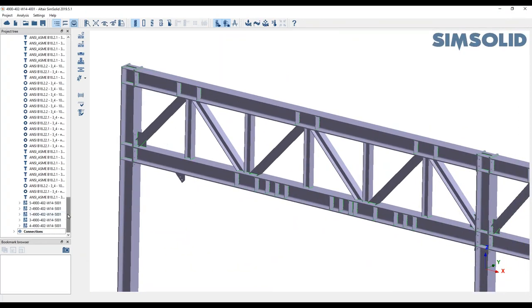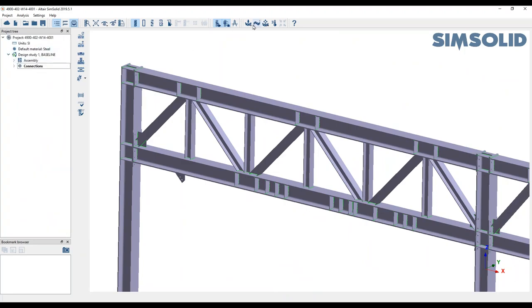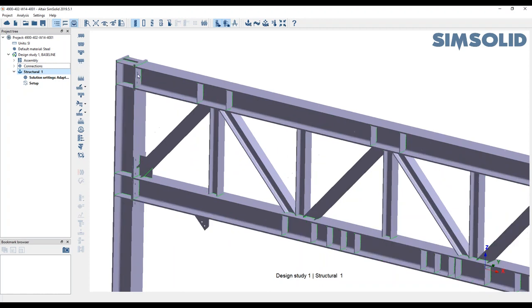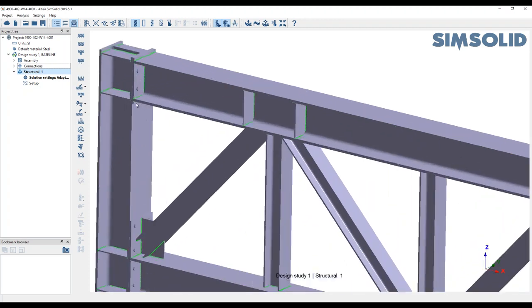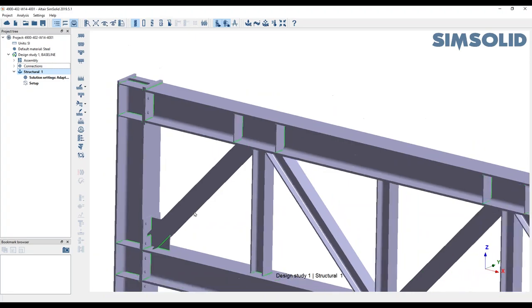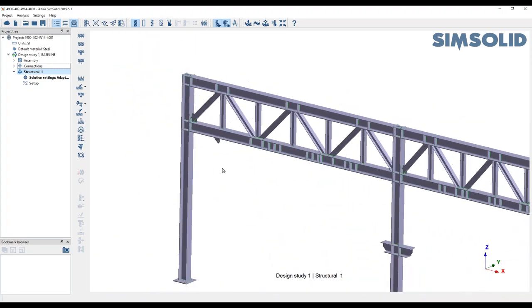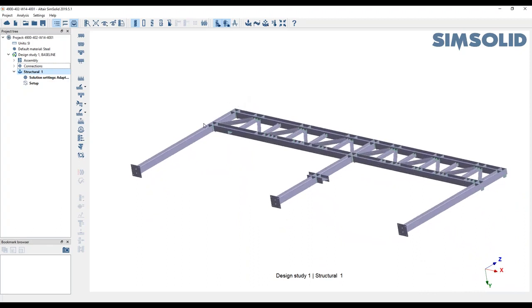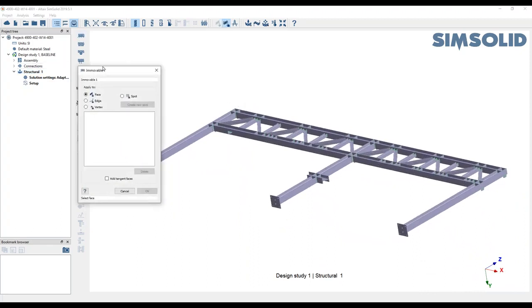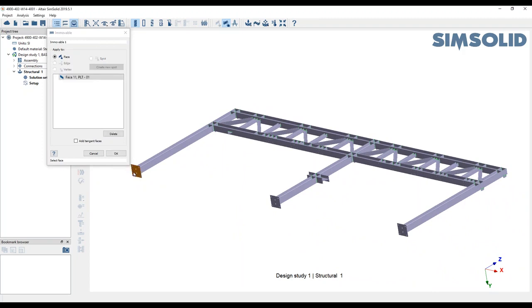I'm going to go and create the stress analysis. So let's just go and create a static linear analysis. So in this example here, I'm going to create a couple of studies, and what's happened here is that everything is bonded. So we're going to run as a bonded analysis, then we'll change the contacts between these plates because in reality they'll be separating or sliding, and you can then basically compare the results. So let's just first of all do the easy task of grounding the columns. So pick that one. So these are fixed to the ground.